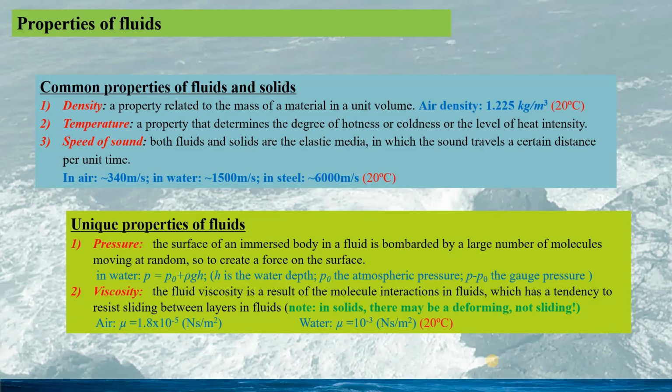Viscosity. The fluid viscosity is a result of the molecular interactions in fluids, which have a tendency to resist sliding between the layers in fluids. This is different from the solids. There might be deforming, not sliding. For the air, its viscosity is 1.8 times 10 to the power of minus 5. And for water, the viscosity is 10 to the power of minus 3.